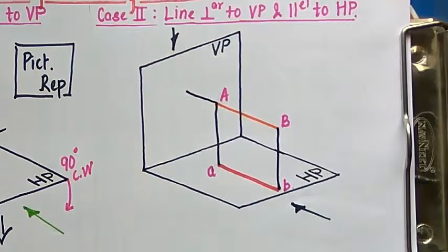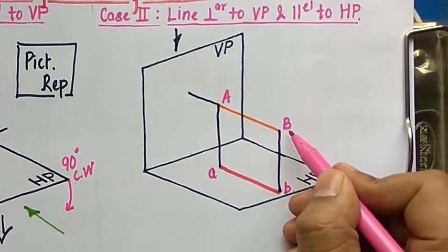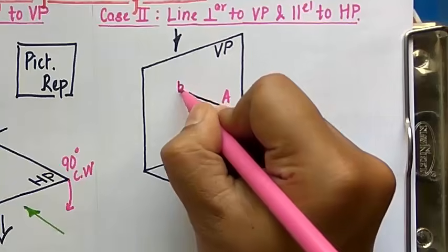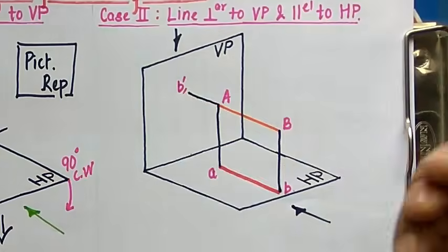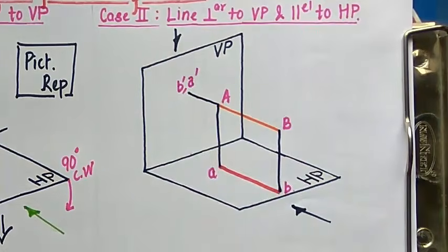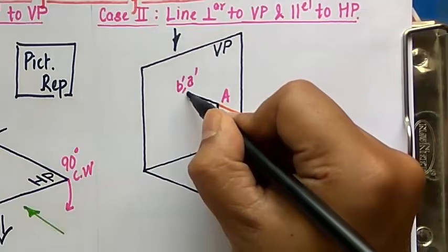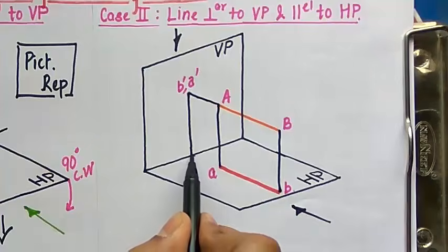This is where you're going to have its front view, and first of all, when you look at this line from the front, you'll observe this point, that is going to be B dash, and behind B dash, overlapping in the form of a point, is point A, that is going to be A dash. Alright, the next thing to do is to join these so-called front view and top view with the help of a line, and we are doing so with this.